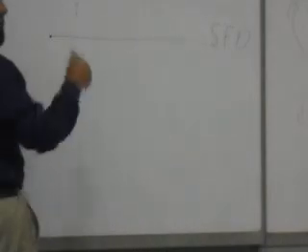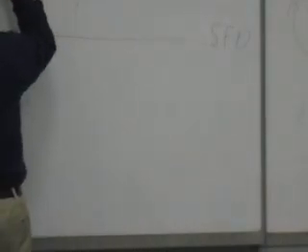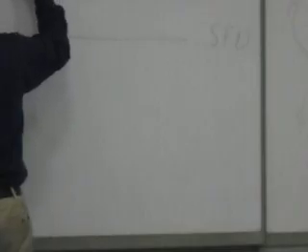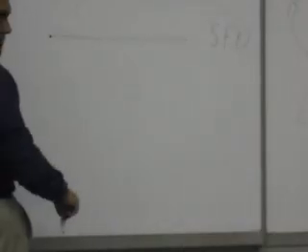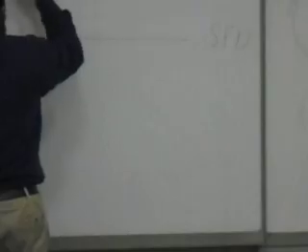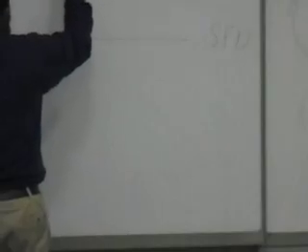That means what's the area of this triangle? That's the only force I'm having, going down. So the area is 0.75 times 6 over 2. This is negative because it's going down. So this is 3 times 0.75, which will be negative 2.25.